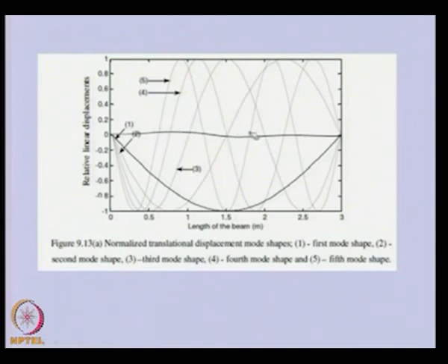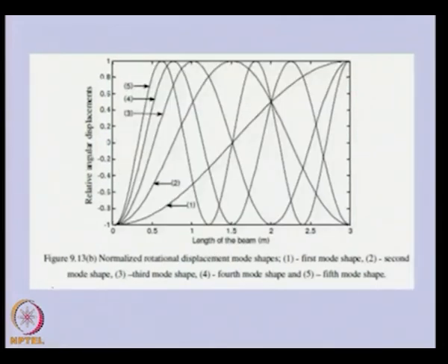at various positions. Those are nothing but the node positions where the displacement will remain 0, as we have already seen in the torsional vibration case also. These nodal positions are more critical; even though the displacements are 0, stresses will be more at these locations. This is corresponding to the slope variation for modes 1, 2, 3, 4.